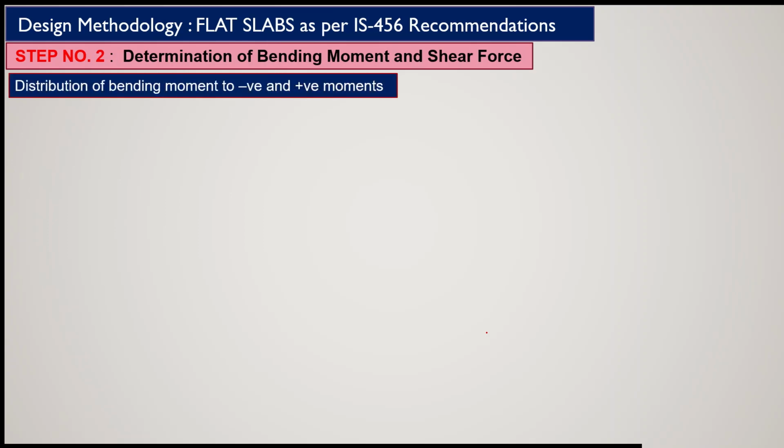Now, as in the previous step, we have discussed how to calculate the total design moment. Now we have to distribute this design moment into negative and positive moments. For this, you have to refer clause number 31.4.3.